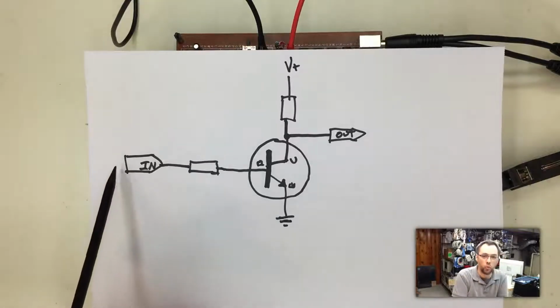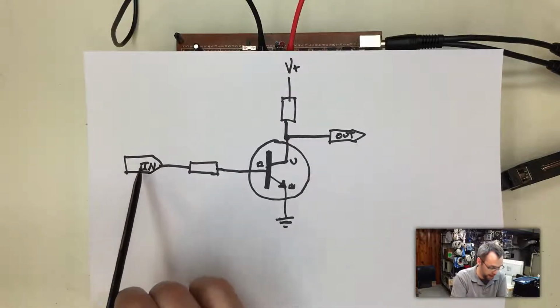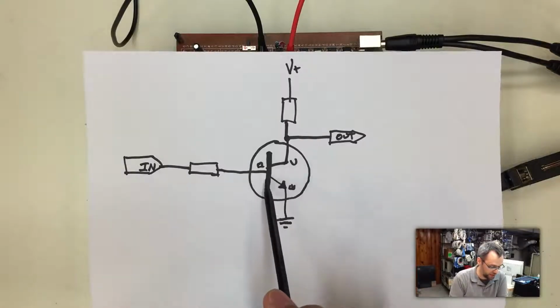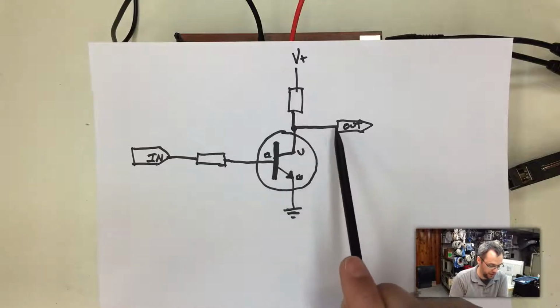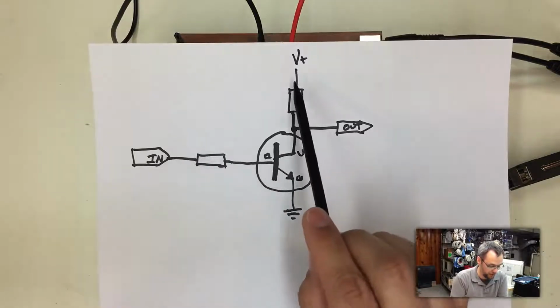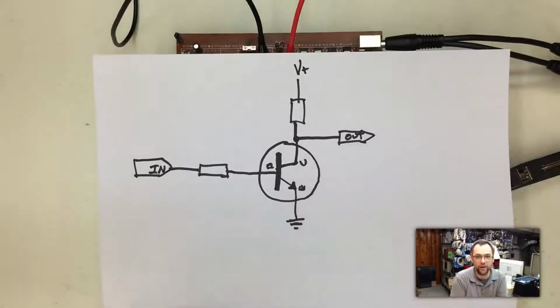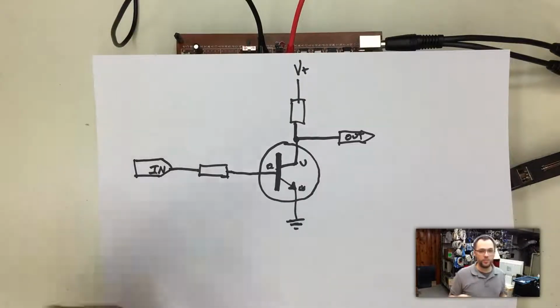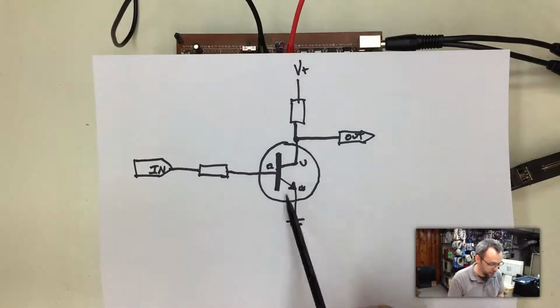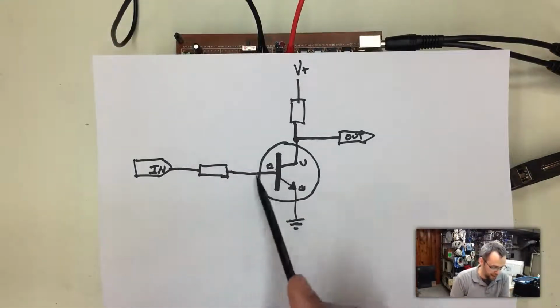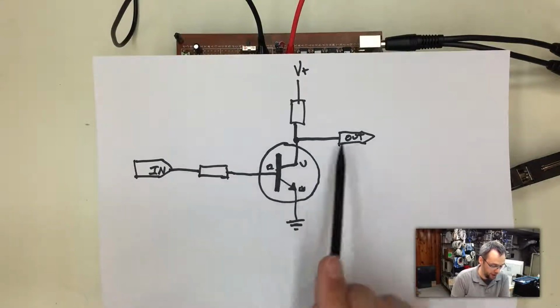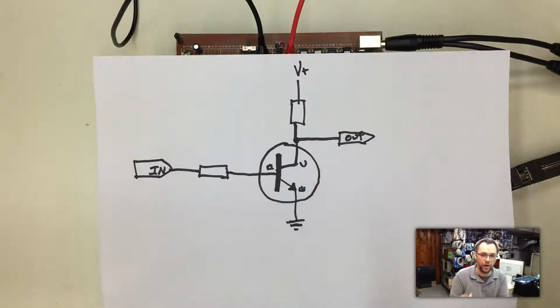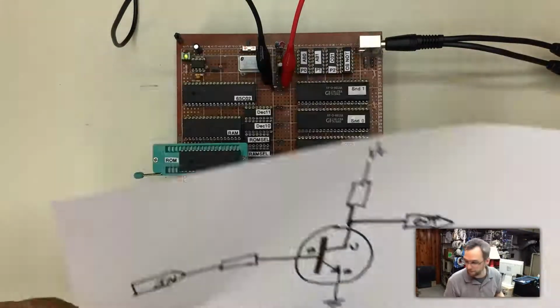If we bring this up to 1, i.e. have voltage on that, it comes in here and it will switch the transistor on. Because there is less resistance here than here, it will shunt this voltage this way, and it turns that off, basically. Now, my description of that could be a little wacky, not quite accurate, but it gives you the idea of how the transistor works as a switch. Basically, by turning this on and off, you're shunting the output on and off in reverse, effectively.